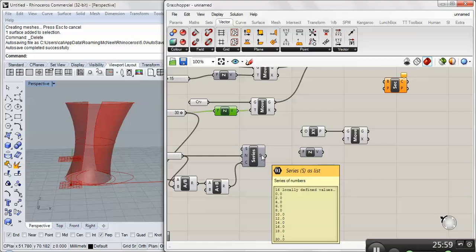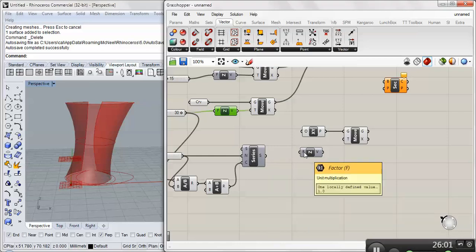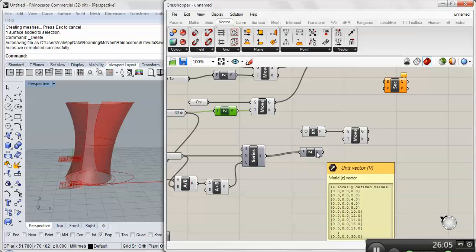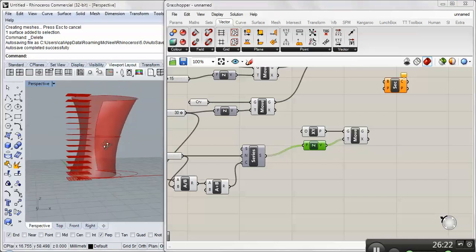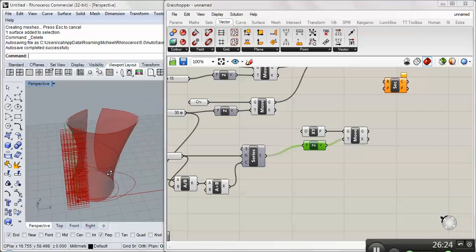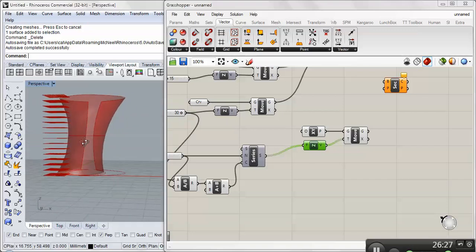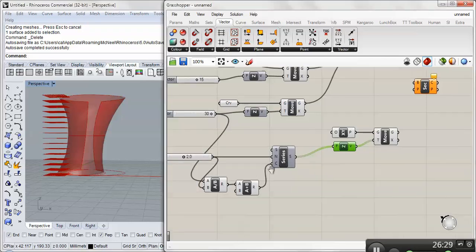When I pull these values in, by default it's set to 1, now I have a translation vector of all of those values. Because move won't work just by giving it distance, you have to give it distance and direction, and that's kind of the definition of a vector. So we'll go ahead and drag that there, and now I should have all my planes at the spacing.